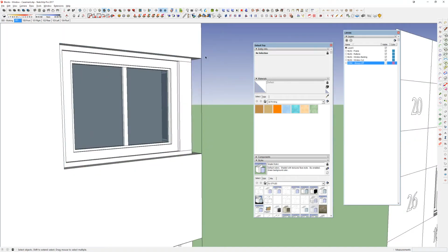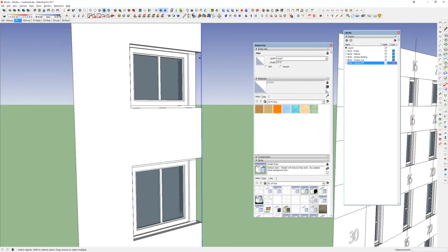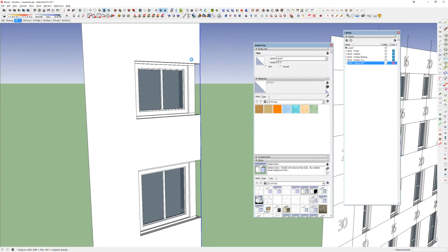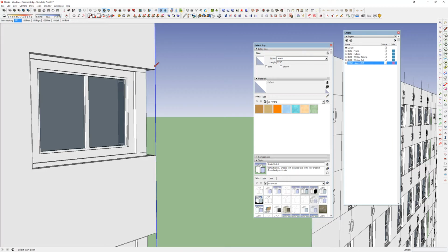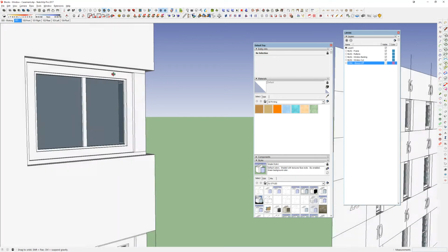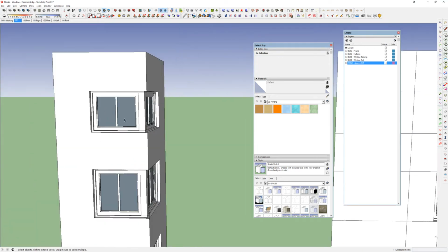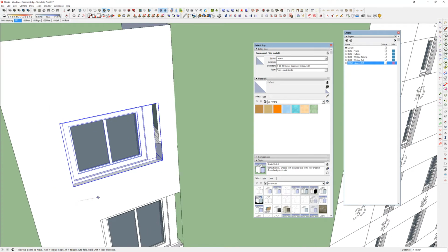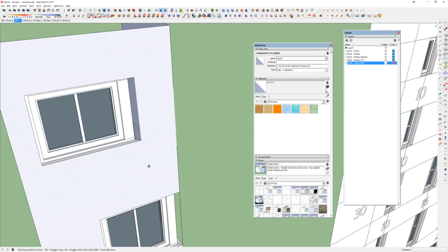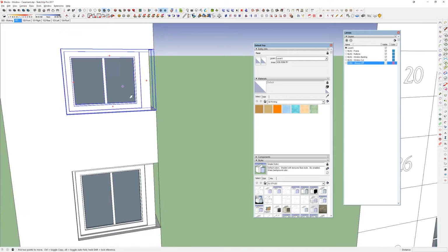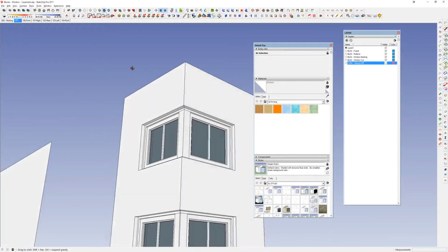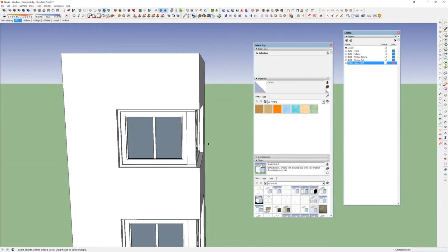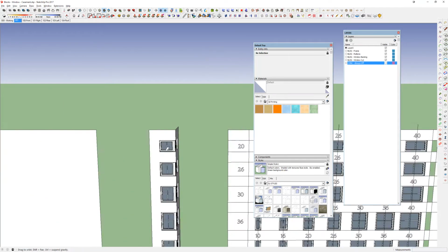The only issue you have is this line, which is the corner of the wall itself. And so if you really want it to be hyper clean about it, I can just draw a second line which cuts that line and add this to always off. And so these are windows that, just like before, I can move around and they cut the window out. But the way that they line up, they actually look like you're creating a nice corner window. So that's what these are.